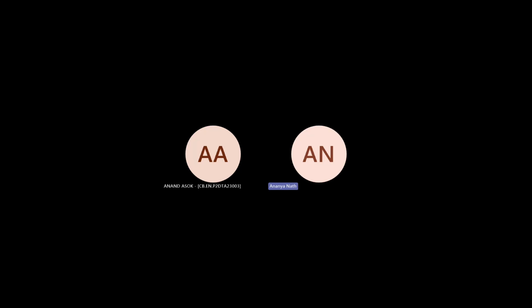For example, in FDM, fused deposition modeling, it's just a nozzle from which the semi-melted plastic filament or semi-melted metal filament comes out. But in the case of VAT photopolymerization, it's liquid resin. Under VAT photopolymerization there are many processes, but for example for SLA, there is a laser beam which cures the resin, each layer. So here the tool is an arrangement of lenses through which the laser comes.